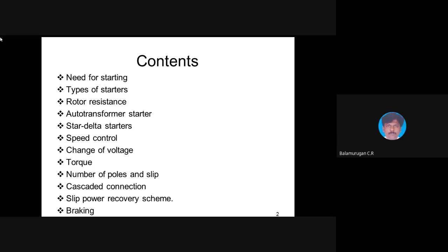Second, to protect the motor from overload. If you apply a mechanical load beyond the rated current, an excess amount of heat will be generated in the machine. Overload is related to the rotor current, which will be beyond the rated value. Then the overload protection senses the excess current and trips the circuit, disconnecting the main supply. And what is the third case? Single phasing. In the three-phase system, we have R, Y, B.